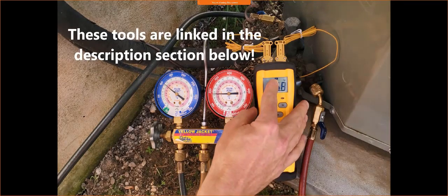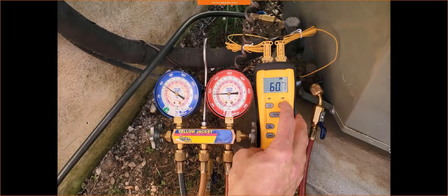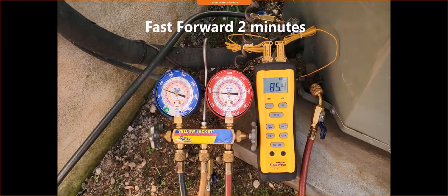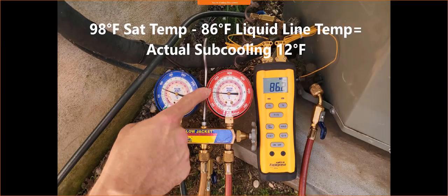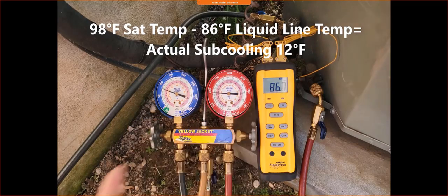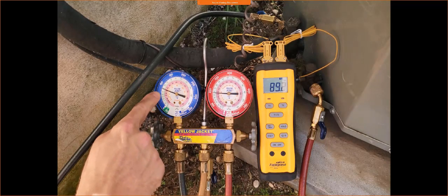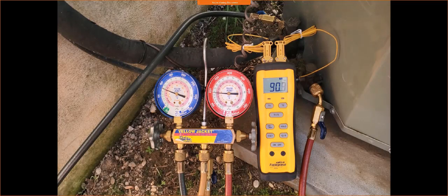Now right here we're reading T1, so that's on the vapor line right here. So I'm just going to go ahead and press T2 and now we'll be on the liquid line measuring the temperature here. If we were to take a measurement of the subcooling right now, on the high side we're reading 98 degrees, so 98 minus 86, and we have about 12 degrees of subcooling. But obviously these are going to move around. If you notice over here, you see the saturated temperature is far above 32 degrees. It's at 50 degrees, and that's because we're just turning this unit on for the first time, and the indoor wet bulb temperature is very high.